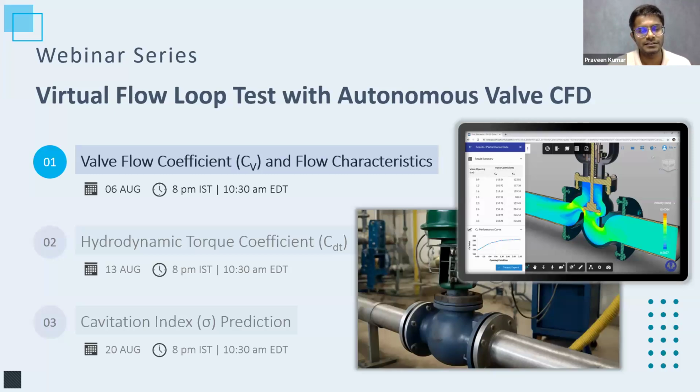Today is the first session of the series. It's a three-part series, with a webinar every Wednesday. We'll be covering three topics under this series of virtual flow loop tests with Autonomous Valve CFD. The first session will focus on valve flow coefficient, CV, and flow characteristics, and how the trim design impacts the flow characteristics using CFD. Next week we'll have a hydrodynamic torque coefficient session, and in the third week, cavitation index prediction.